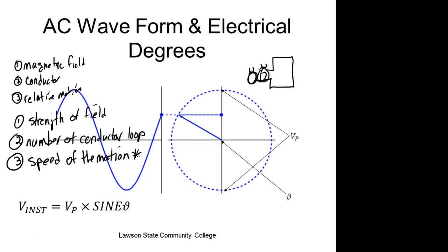So we can regulate this stuff, and that's what's on Alabama Power. They regulate their output voltage, but the problem is they regulate it at the power station, right? From then on, they're depending on transformers. So that's why it's such a wide range. 120 volts plus or minus 10% is legal. So that would be anywhere from 90-something volts up to almost, would still be considered legal to your house.